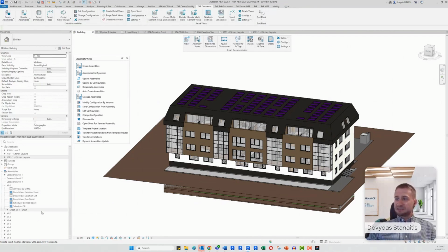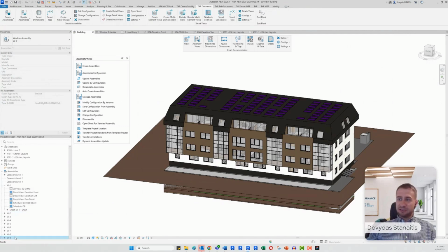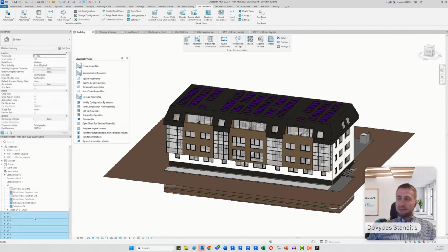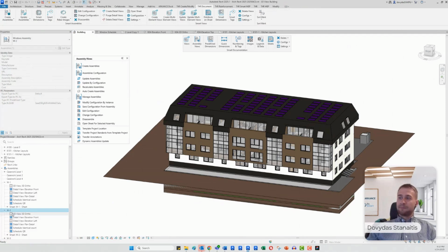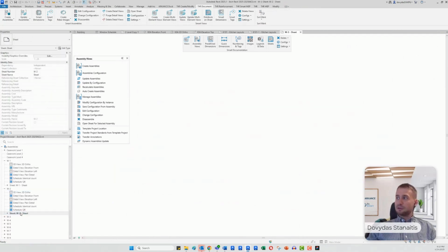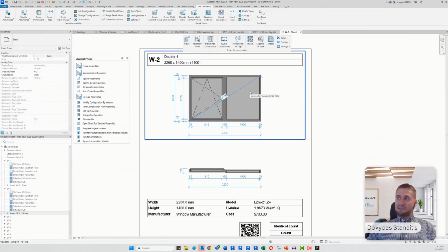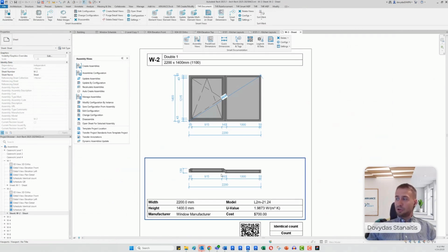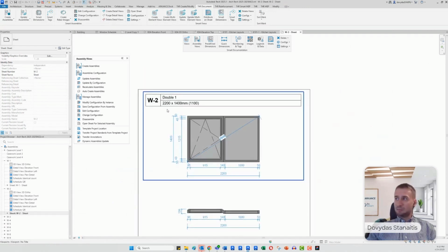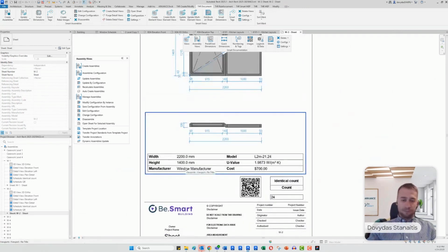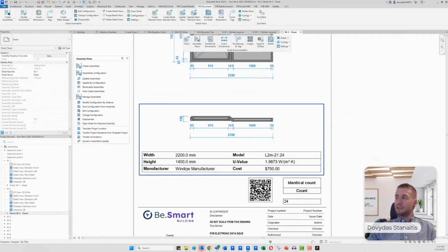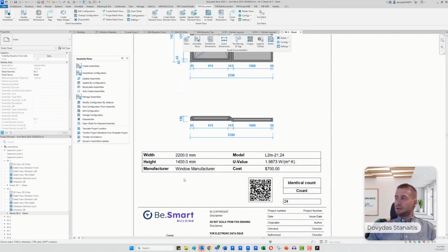So now that this is finished, the result is 8 assemblies that have been created. And we can take a look at how they look. So again, I have specified to create a front view and the top elevation, which I tagged. I've placed some information about each window as well, in form of tags. And these tags also give me information, pull some family parameters from the window family.